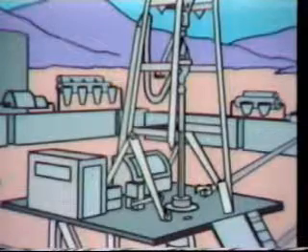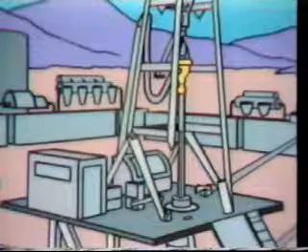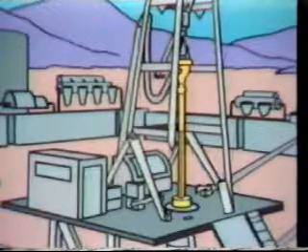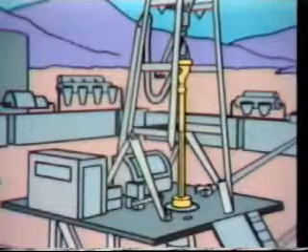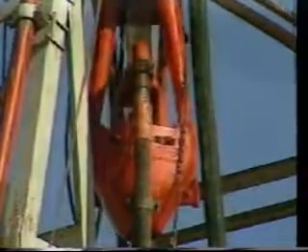The components of the drilling rig involved in rotation are the swivel, the Kelly bushing, and the rotary table. The swivel allows the suspended drill stem to rotate while supporting its weight and providing a pressure-tight connection for the circulation of drilling fluid.